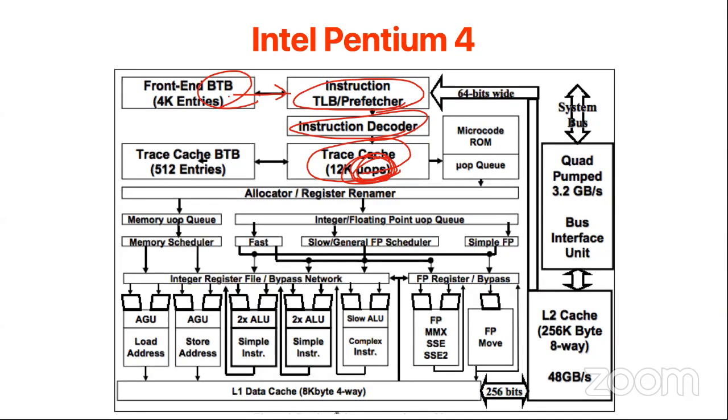And here you see there's a micro-op. Let me explain a little bit. Although x86 processors still present an illusion that it's a CISC instruction set architecture processor, and indeed this part and this part of the front end all support those CISC instructions, the instruction decoder in Intel or AMD processors actually turns an x86 instruction into several RISC-processor-like micro-operations.